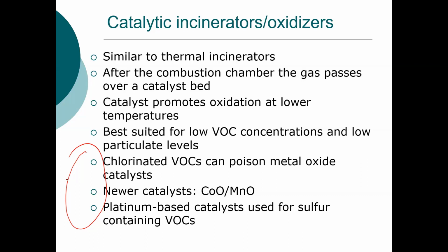So for instance, let's say you're looking at a system where you have groundwater contaminated by a combination of gasoline and dry cleaning solvents, trichloroethylene, tetrachloroethylene. So you've got both compounds like benzene, toluene, ethylbenzene, and you have chlorinated solvents.